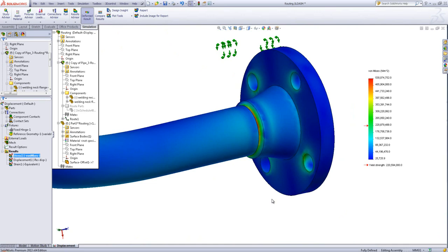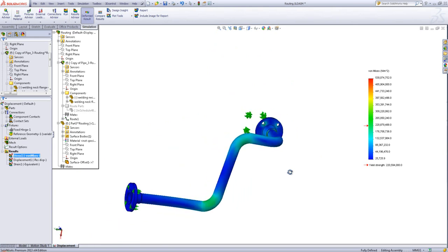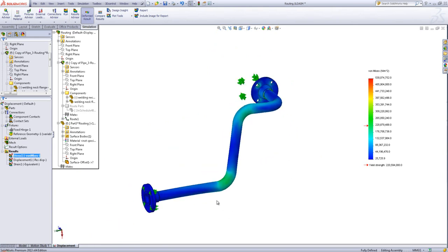Finite element analysis doesn't really like contacts like that, because what we're doing in this case is bonding 2 bodies together just by an infinitely thin edge. Because we've got elements on that infinitely thin edge that have to move relative to the pipe, and we've got elements immediately adjacent to those that can move somewhat freely, we do get large spikes in the stress values, and these are what are referred to as singularities. So we would negate these. In actual fact, I'm going to show you how to concentrate on just the pipe in a moment.